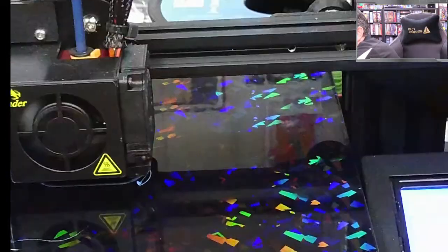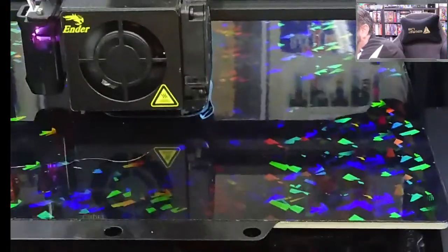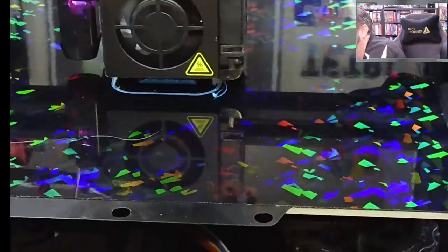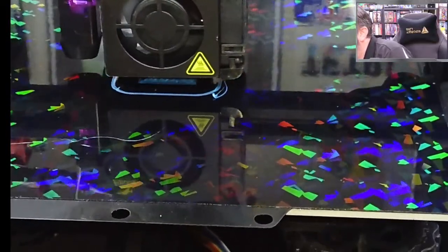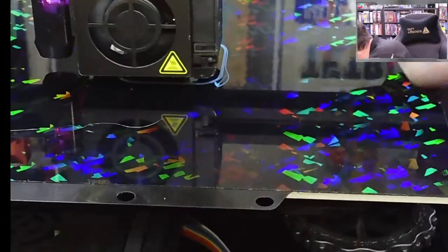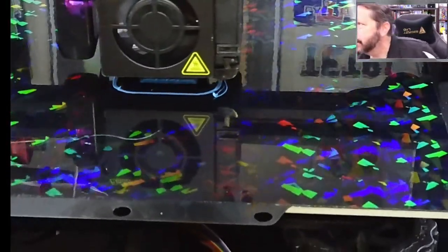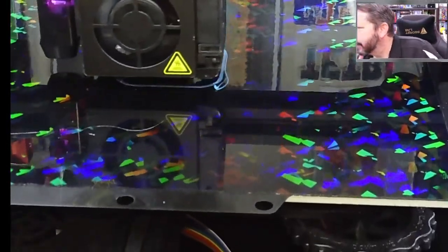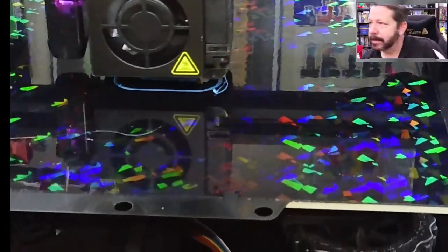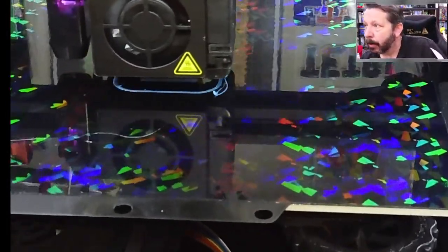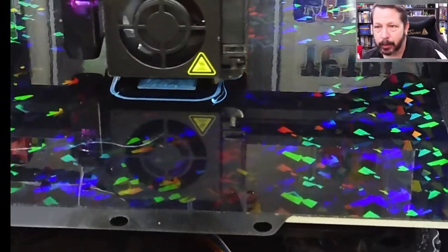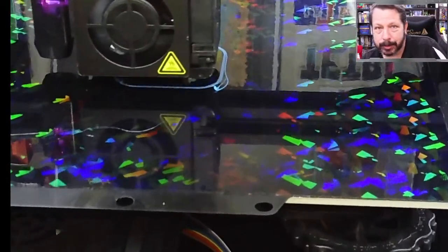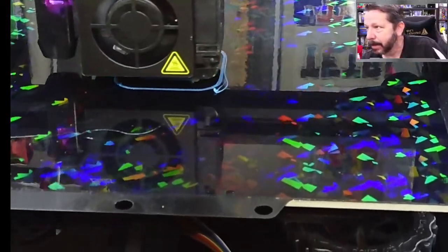I don't know how close I can get in there. Oh, I can't. Oh, it's kind of lumpy looking in that picture. And I can see it in person. So that lumpiness that you can see, what that is, I am over extruding or my nozzle is too close to the bed. Now I'm not particularly worried about it because I'm more interested in getting a good squish on the bottom side, and that lumpiness is going to get covered up.